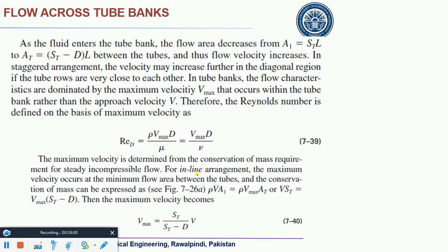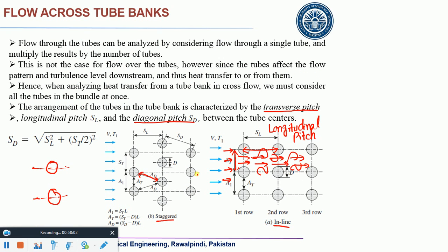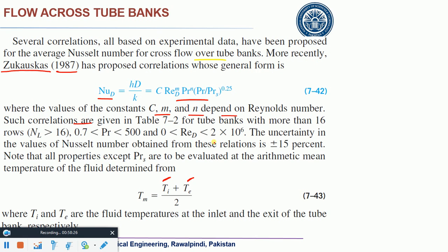It means I am just talking about this inlet temperature. This is the inlet temperature, where the flow is coming into the shell, onto that bank of tubes, and this is the outlet temperature, exit, right? So you would not consider this Ts on the surface of the tubes. You would consider this inlet and this exit. So this is the mean temperature,